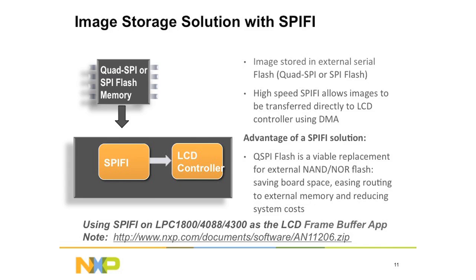What it basically does is, one, it's a Quad SPI interface, and it actually showcases the external memory, a Quad SPI flash memory, and it maps it just as if it would be internal memory, internal flash. So the 4357 itself has 1 meg internal flash as well. But our board right now supports 256 megabytes of flash.